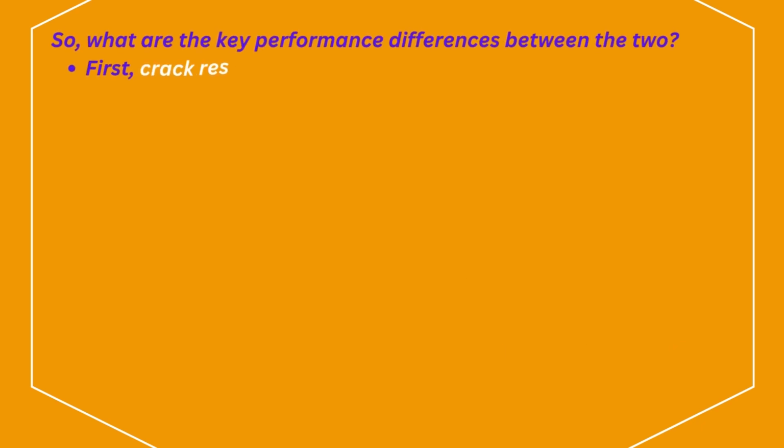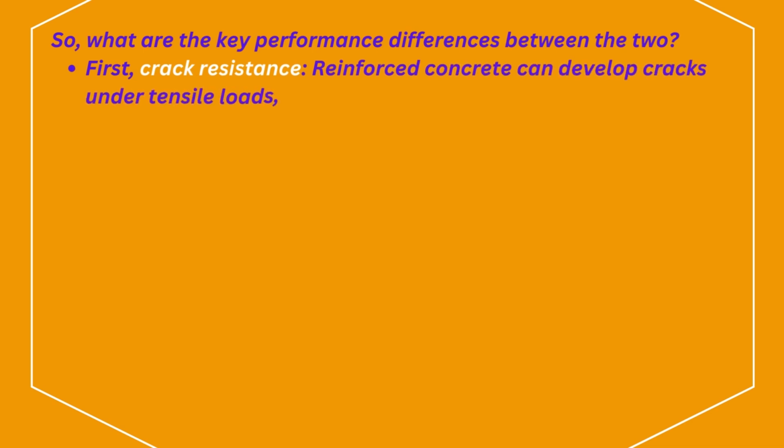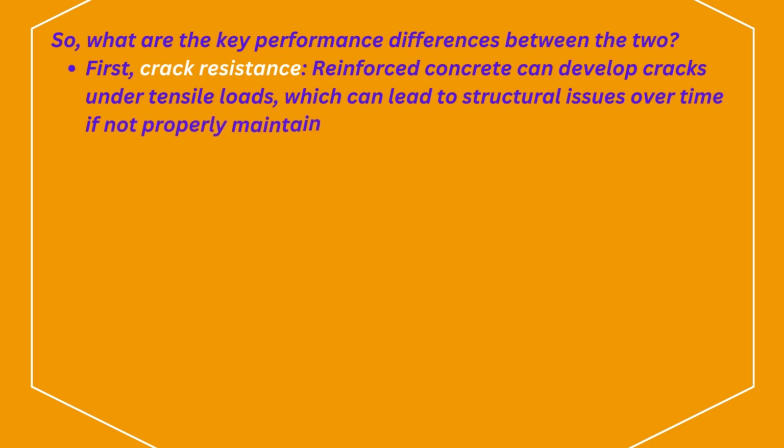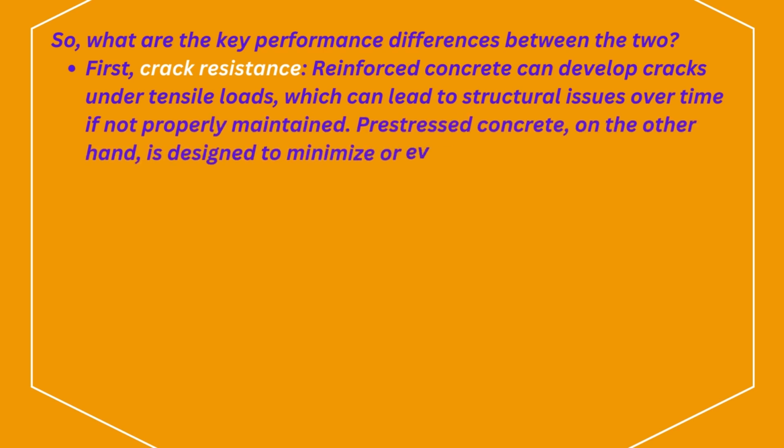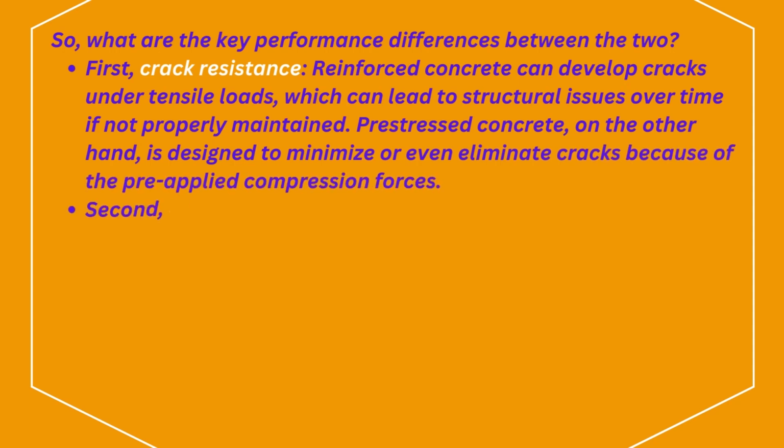First, crack resistance. Reinforced concrete can develop cracks under tensile loads, which can lead to structural issues over time if not properly maintained. Pre-stressed concrete, on the other hand, is designed to minimize or even eliminate cracks because of the pre-applied compression forces. Second, load-bearing capacity.